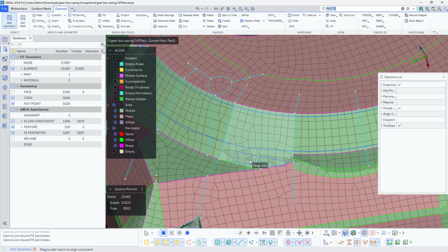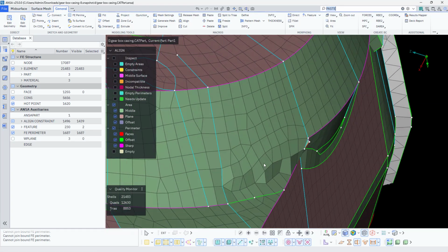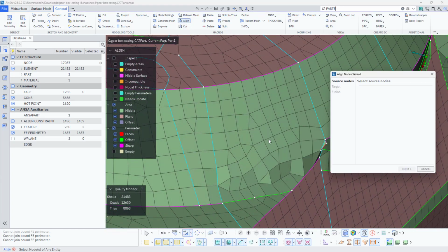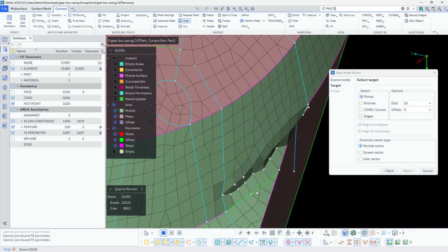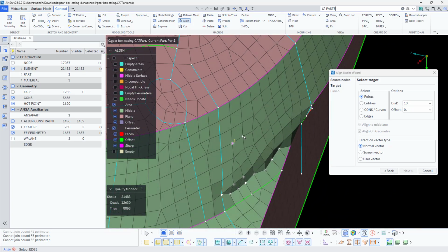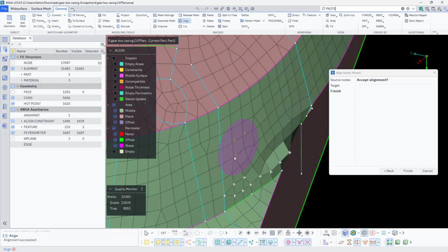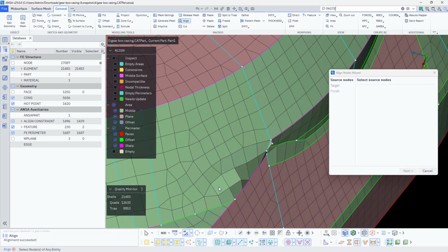By just selecting the grids and defining the plane or a face, you are able to align the grids exactly to the flat surface. Okay, let's do the same. We can just select the align tool and define these grids. Yeah, and you can just click on next and define 3 points so that it can take a planar section like this, and it is aligned here, right?